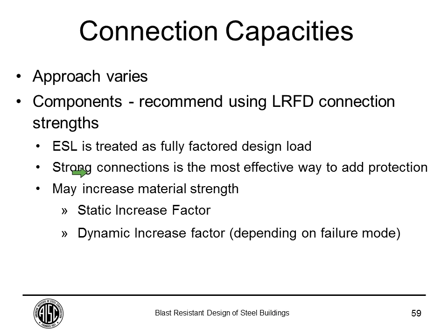Obviously, I have said this many times already, strong connections are the best way to include ductility into your design. And depending on the member response, you may or may not increase the material strength. The static increase factor, I think you can add, because that's a representation of a real strength of the material. The dynamic increase factor depends on the mode of failure that you're looking at.